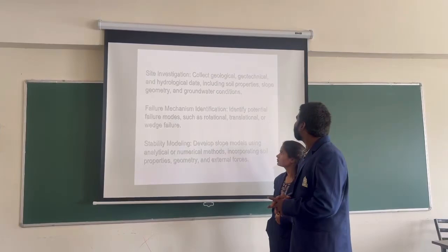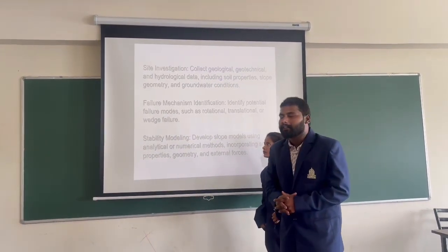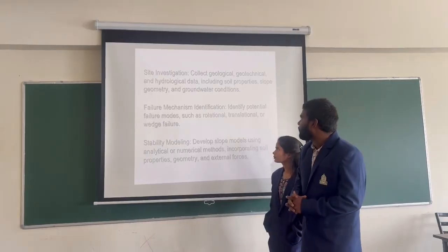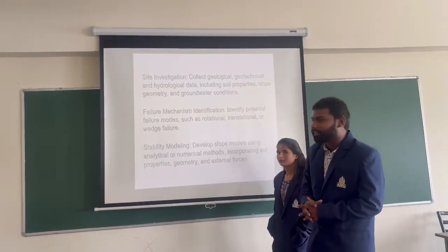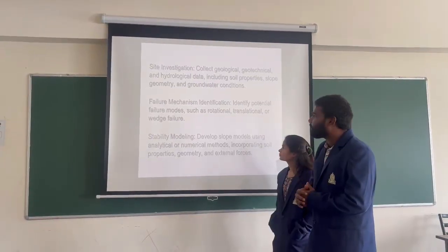The procedure for the project: first, site investigation, collecting geological, geotechnical and hydrological data, including soil properties and slope calculations. Then failure mechanisms identification: identify potential failure modes such as rotational, translational or wedge failures.